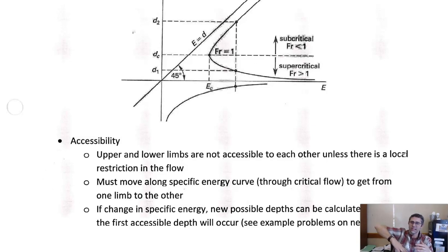So we might have cases where we want to force the flow from the supercritical flow that we wanted into a subcritical flow, where we'll get the velocity to drop and lower that erosive force, lower the stress on the channel sides, and get it into a subcritical flow range. So again, we're putting controls in place to force flow from one regime to the other.